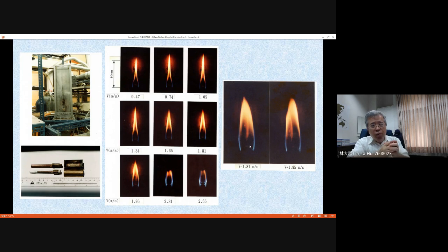The droplet size is very small, but you believe there is still a small eddy in the downstream of your droplet. They have some recirculation zone. If you increase your velocity further, you will find the flame cannot be stabilized. Some flames already dip off since they cannot stabilize near the edge of your cylinder. There is a possibility for them to dip off.